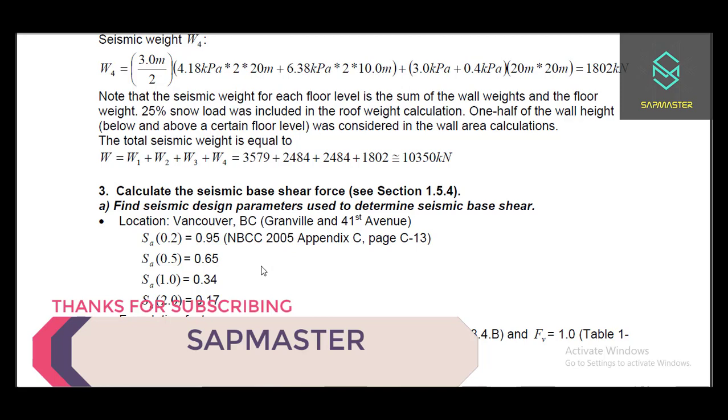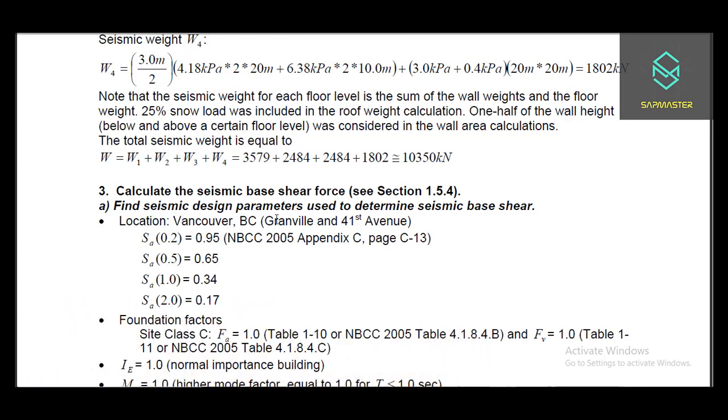Now, after calculating the seismic load, it's time to calculate the seismic base shear force. For this one, you have to find the seismic design parameters used to determine seismic base shear, which is the acceleration in 4 different periods, where you can find them from NBC.